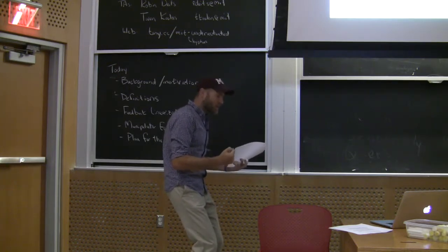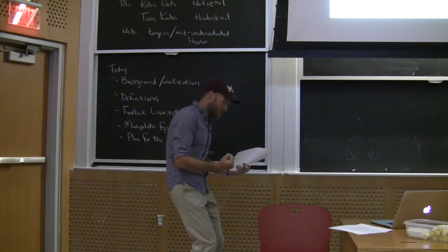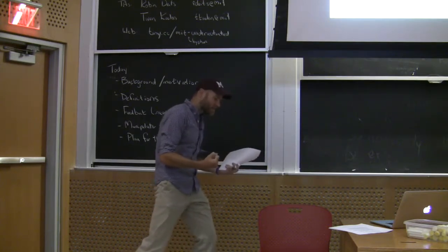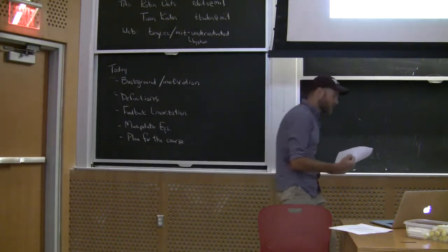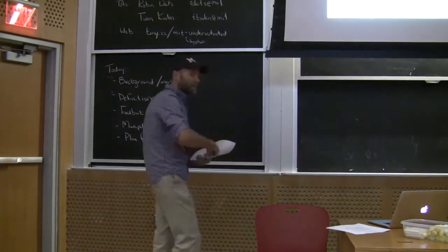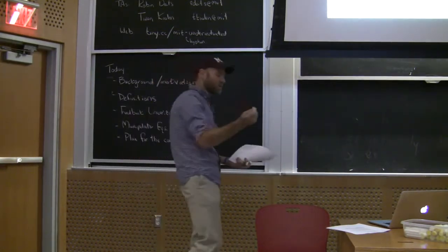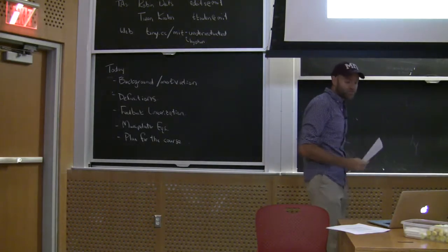Okay, but also Asimo's doing more than that. It's actually using very high gain feedback to effectively cancel out the dynamics of its legs when it's walking around. So in some way you could say that Asimo is sort of walking like a robotic arm that you might use on an assembly room floor, and really not walking like a human.